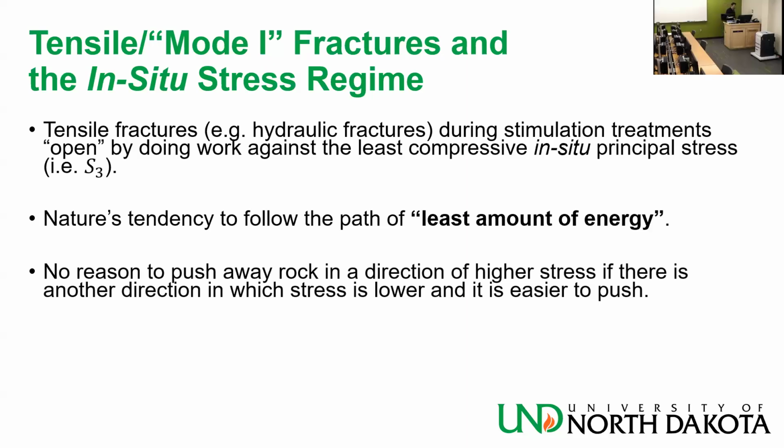There is no reason to push away rock in a direction of higher stress if there is another direction in which the stress is lower and it's easier to push. It's like electricity, it always takes the easiest path downwards. In this case, the fracture will open in the direction that requires the least stress. And because it's opening mode, it should be perpendicular to that. So I'm opening against that least compressive stress.